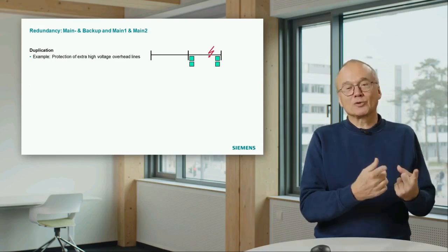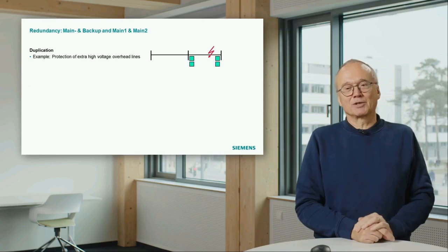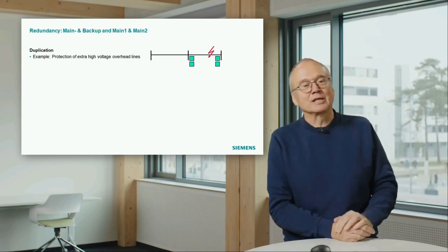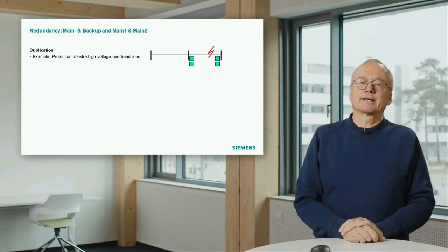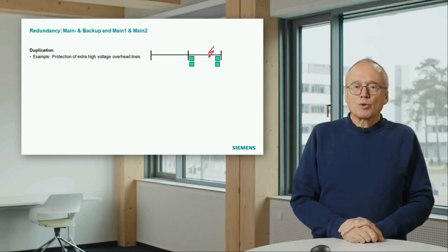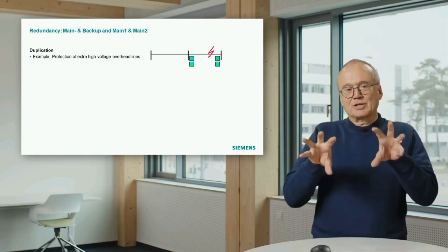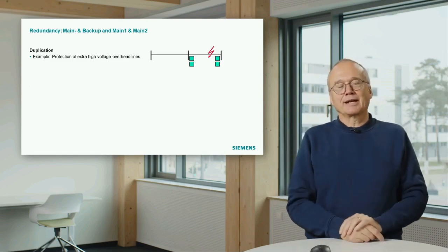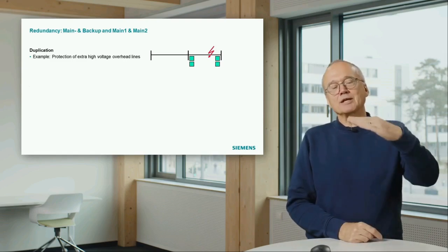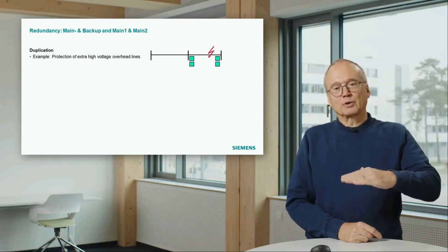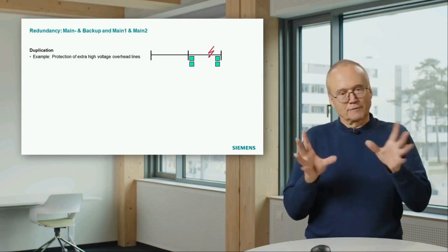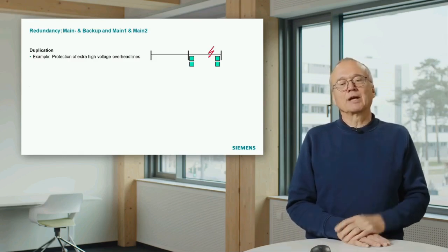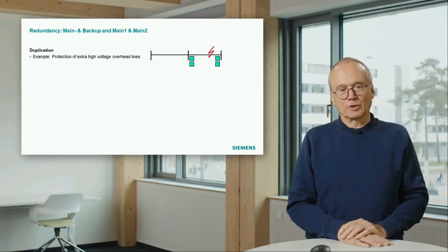That means you will only trip the breaker if both give a trip signal. That is again this discussion about dependability and security. But state of the art in this context is that both relays or both protection schemes are independent. That means both relays can trip. That means you can even take one of the two protections temporarily out of service for maintenance or some changes. Then the other one will remain in operation, and if there is a short circuit, it will trip.